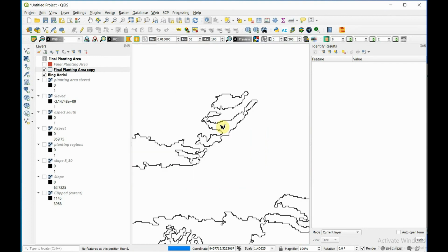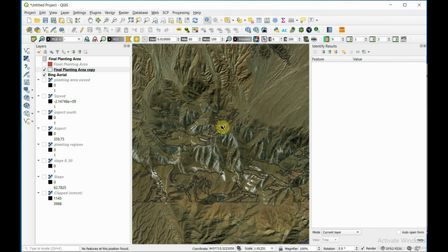There might be a few spots where, instead of 90 to 270, maybe we could have done something more like 75 to 295, adding a little extra, because during the summer, because of our latitude, the sun actually rises and sets at a different degree than just 90 and 270. That would be more appropriate at different latitudes, but because of where we are, the trees would get enough sun at different aspects that it might be worth going back and fixing our aspect map a little bit and going back through the process to refine this model.